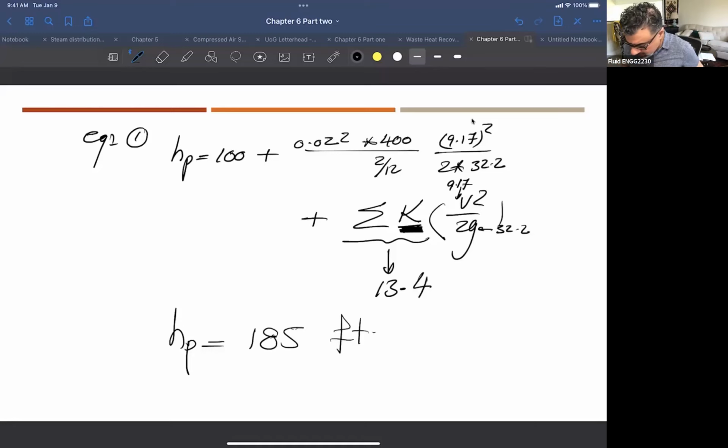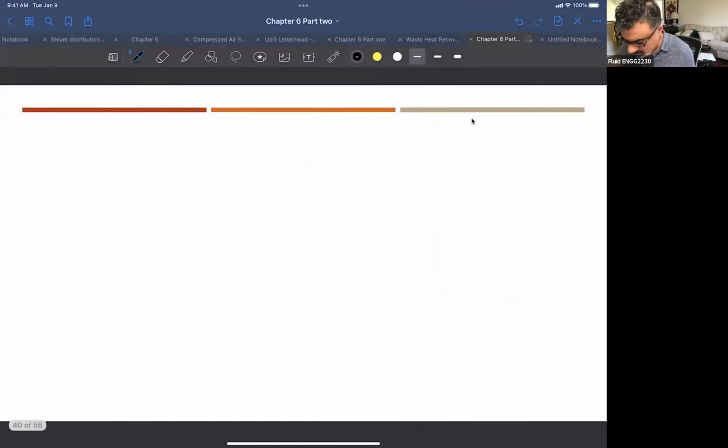Okay, so now in order to drive the flow at 0.2 feet cubed per second in this system, I needed a head increase from the pump, and the head of the pump is the energy, right? So basically, this is the energy for the Bernoulli equation, each term representing energy, but in terms of feet. You need to find out, for example, this energy or the power. What is the difference between power and head? What is the power? Pump power.